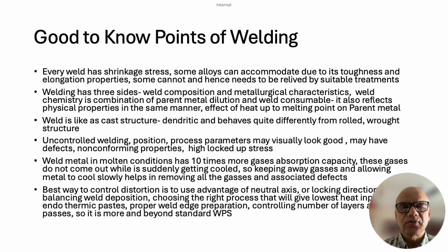And if there are service conditions with cyclicity at higher temperatures, higher pressures or higher loads, this entrapped hydrogen gas in these porosities or inclusions, which has already created a small notch because of its high pressure, starts propagating that notch into a crack, and a phenomenon called cold cracking or delayed cracking takes place.